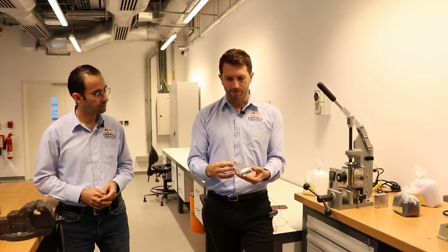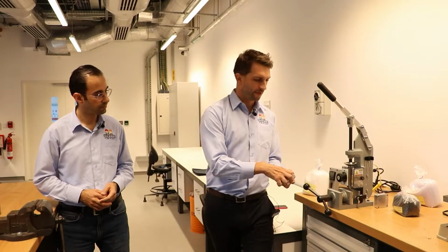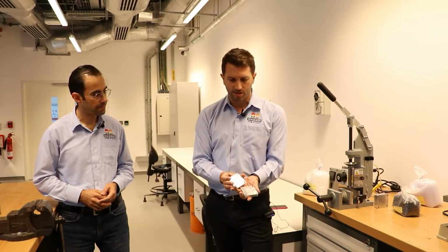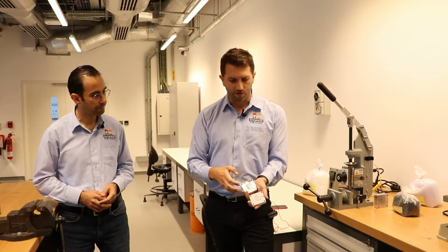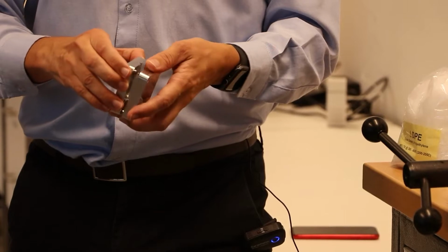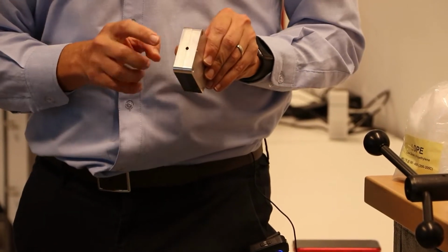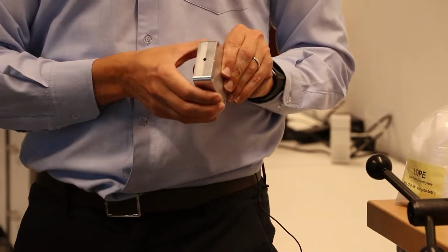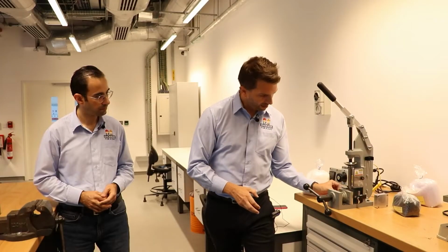Now in the bottom here, we're able to put in a mold, something that looks a little bit like this. And it is essentially the concave, or the shape that we want to achieve. We put that mold together, and you can see it has a single injection site, what we'd call an injection site. And we clamp it in here in the bottom of our injection molding.